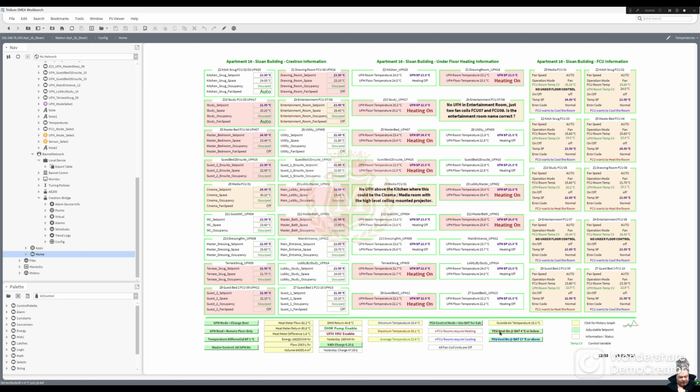They've asked for the fan coils to be on heat if outside air goes below 4 degrees, and to do cooling if outside air goes above 17 degrees. So at the moment the fan coil units are off, regardless of heating and cooling. But we've got some underfloor temperatures on here in red, and that's because the set point is 22 there and it's only 20, and 24 there and it's only 23.4 there, so hence that's why they're heating.